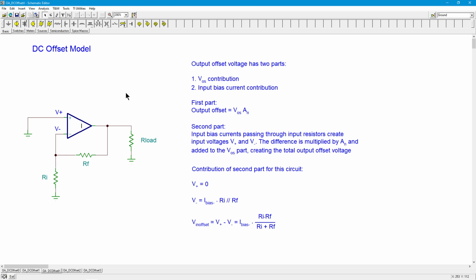So which transistor has the higher beta? I don't know. Luck of the draw. The current coming into the plus might be higher than the current coming into the minus, and it's just as possible the other way around. It's this unknowing that leads us to the ambiguity. So all we can really do here is compute how bad this is.